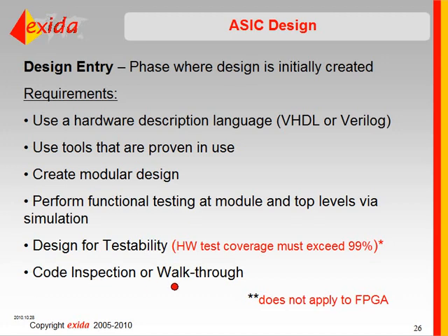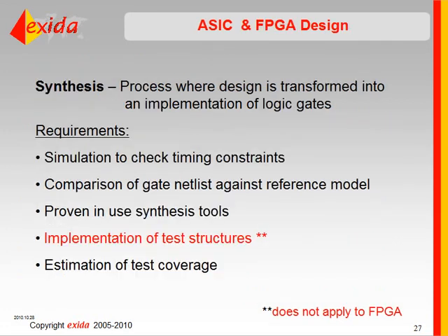And then you need to do a code inspection or a walkthrough, just like you would do for software. This is needed for the VHDL and Verilog code. Notice the items in red here don't apply to FPGA. So these requirements in general apply to both ASICs and FPGAs, but the ASIC requirements are more rigorous, and so there are a few requirements that we'll point out on these slides that don't apply to the FPGAs.